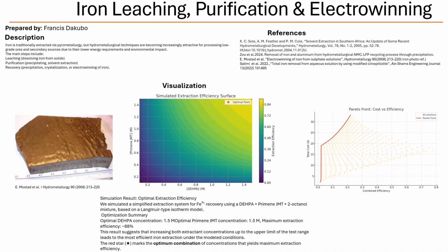Now, when you're trying to model these real-world industrial processes, you run into some snags. Snags is an understatement. Like predicting the pH accurately in those countercurrent systems, that's where two streams flow in opposite directions, multiple stages. It gets tricky because these solutions are super concentrated. Salt City. Yeah. And those high salt levels mess with the theoretical pH prediction. So the researchers had to get creative. They observed how much iron was extracted and then connected that to the actual pH changes they saw. That gave them a relationship, an empirical one, that they plugged back into their models. So it's not just about the theory. You've got to have that real-world data. Exactly. To get a model that actually works, you need both the theoretical foundation and the real-world adjustments.